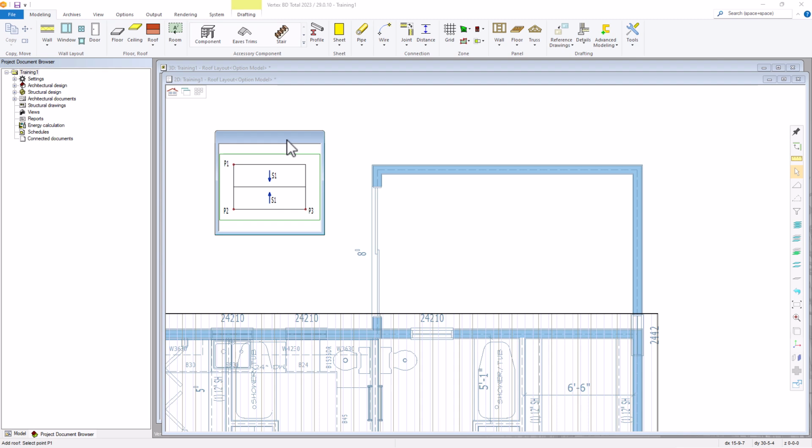Now with a basic roof shape, a diagram appears with the selection points and the order in which they need to be made to create the roof shape. We have a point 1, point 2, point 3. This is how our selections need to be made in order to get this shape on the screen. But we want our gable or our ridge to run vertical. So we need to visually look at this and rotate it clockwise. So if we rotate this clockwise, then our point 1 would be at the top, point 2 on the opposite left corner, and then point 3 down. So you kind of need to mentally visualize this.